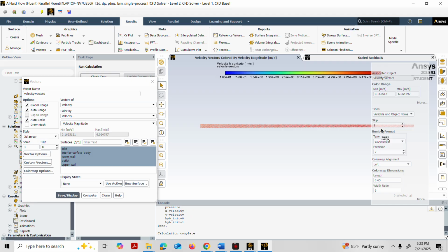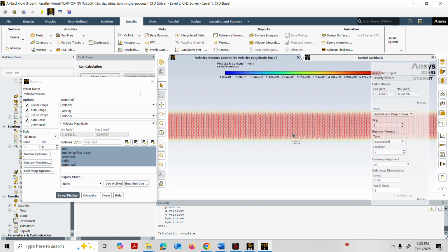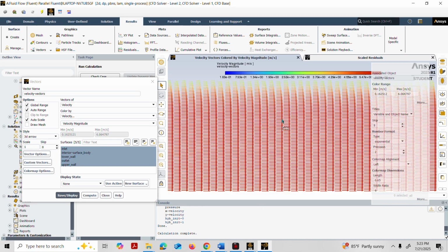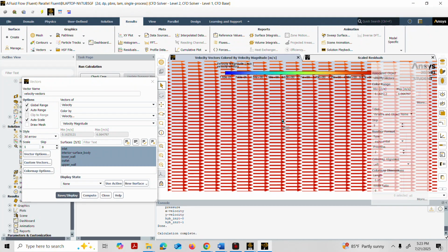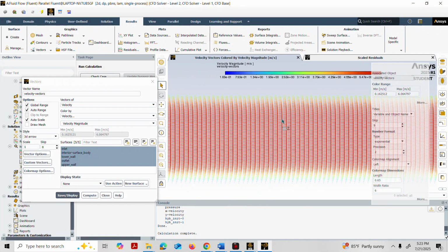I'm going to zoom in so you can see the velocity vectors. So you zoom in, and we went real small, so I have to zoom in a lot. You can see the arrows, and those are the velocity vectors at that level in the pipe. We have boundary layer prominent at the bottom, and we have also some boundary layer at the top. And we have development in between both of those boundary layers, and it's an asymmetric development. Let me just look at my notes.